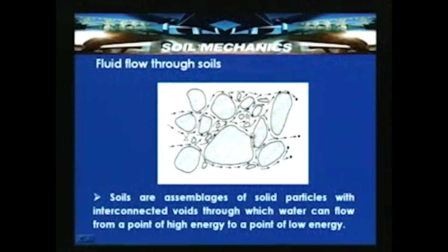Before discussing that, in this slide, as we have seen in the previous lecture, the soil is an assemblage of particles. In this particular slide, the granular particles are shown like solid grains, which is possible in coarse grained soils. But in the case of clay soils, depending upon the structure, it can have a flocculent structure or a dispersed structure, or a semi flocculent or dispersed structure.